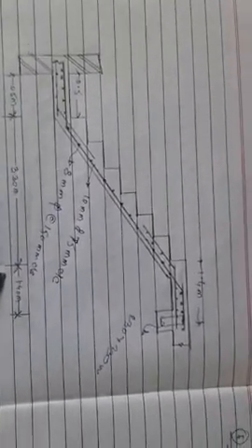Then we go for the arrangement, that is the reinforcement detailing in the staircase. Here this is your distribution steel, 8 mm phi at 150 mm center to center. This is your main steel, which is 10 mm phi at 75 mm center to center. This is the position of your column, that is 230 mm by 230 mm. This is your landing having width equal to 1.40. This is your passage, 0.5 meter, and this is your going, 3.30 meter.